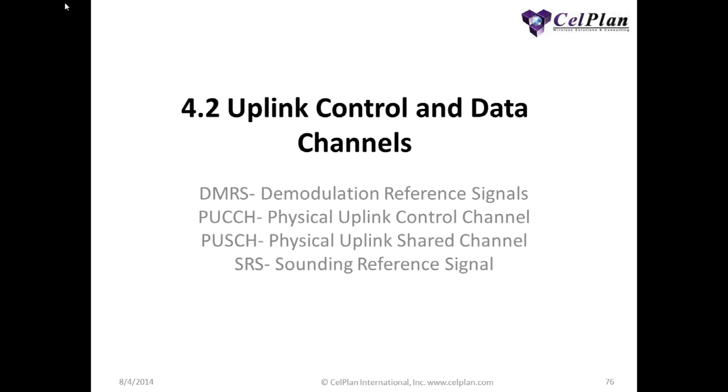Well, it depends on how fast it is moving. And of course, the UE doesn't know how fast it is moving. So this has to be specified in one of the timers that is sent in one of the SIBs. So basically, the UE will have to adjust according to this timer, or when it moves from one cell to the other, or when it goes to a disconnected state, and then when it comes back, it has again to adjust the timing advance.